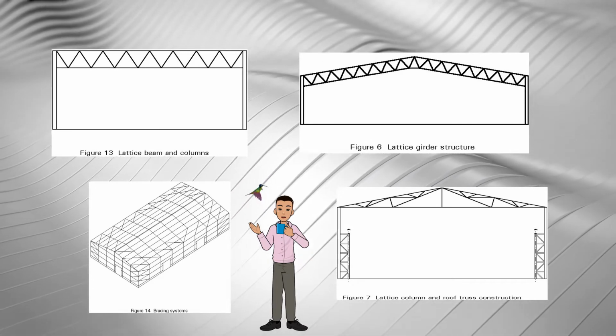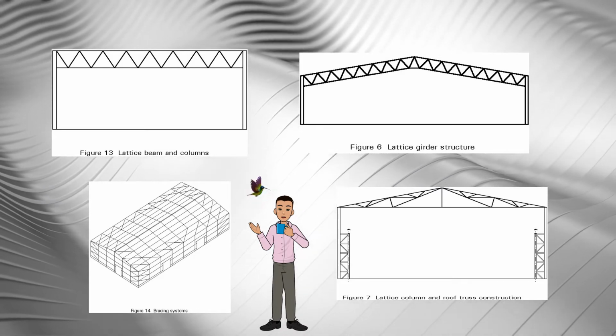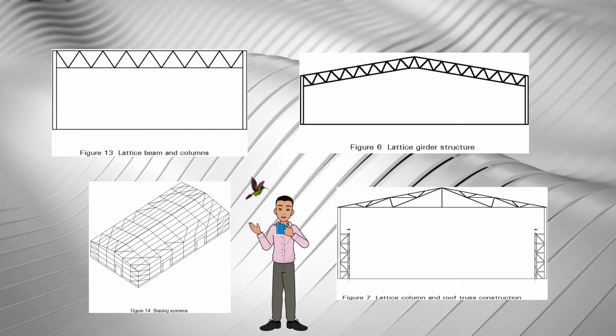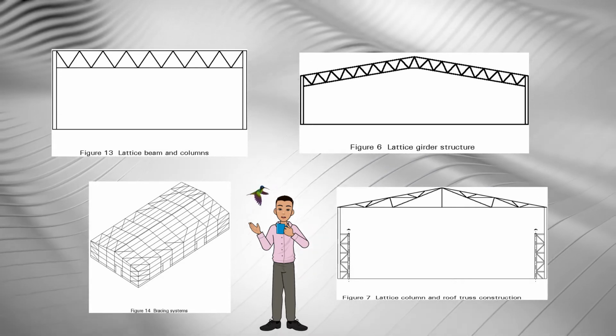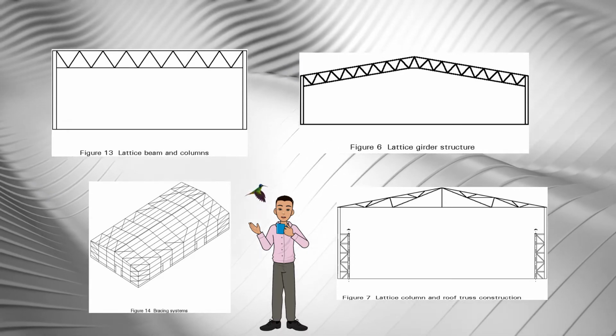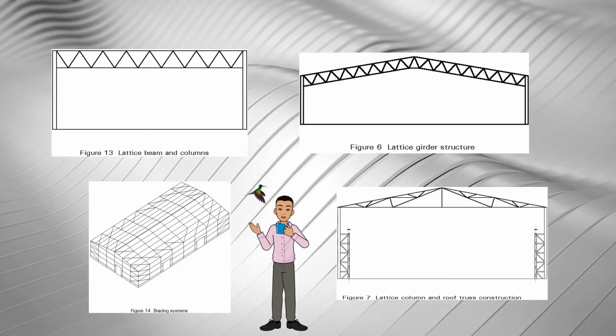Bracing members for industrial buildings commonly use circular hollow sections, rods, or angles. When cranage is provided, the stability requirements need further examination, since longitudinal and transverse surge from the crane increases the forces in the bracing system.